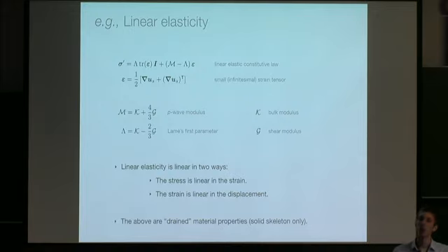Are you implying that the strain should be defined differently if it is nonlinear elasticity? Yes. Although I have to say, when I started doing these things, I initially felt that strain was fairly clear because strain is calculated from displacement, which is all kinematics, and that the relationship between stress and strain was a bit fuzzy because this is where constitutive modeling comes in. But actually, I think it's better to think of stress as being the thing that's very clearly defined because it comes from force balance, and strain is where things get a little bit fuzzy because strain has to do with how you relate stress to strain energy, and there's various definitions.